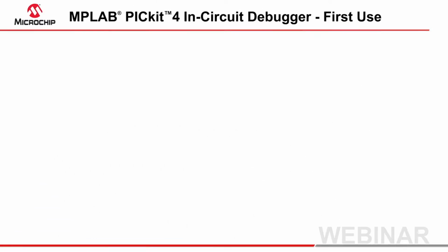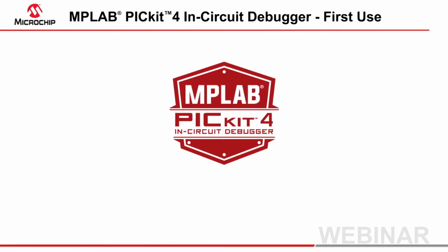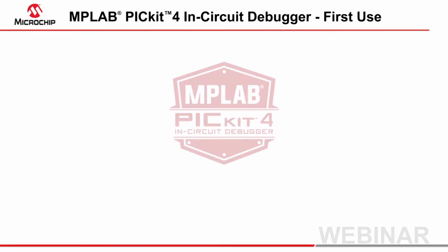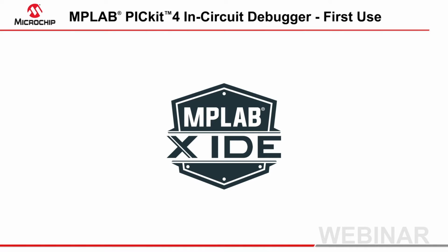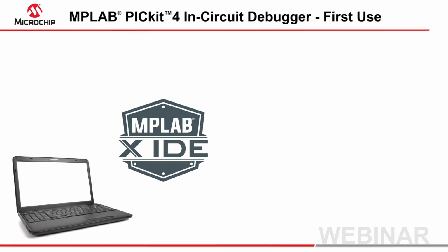This webinar will guide first-time users of the Microchip PICkit 4 through the steps necessary to set up the in-circuit debugger ready for use. Before you begin, ensure you have installed version 4.15 or later of the MPLAB X IDE.